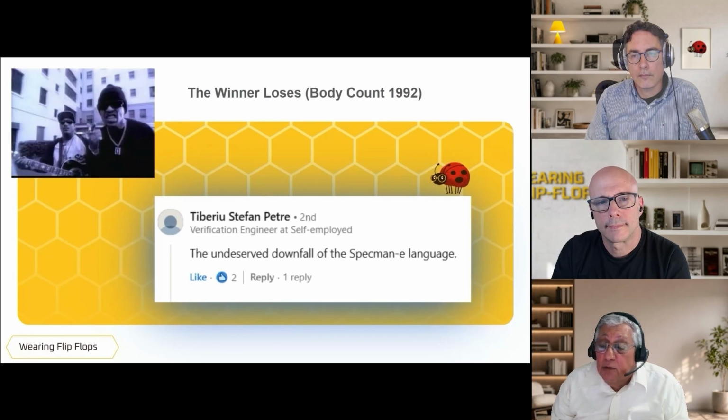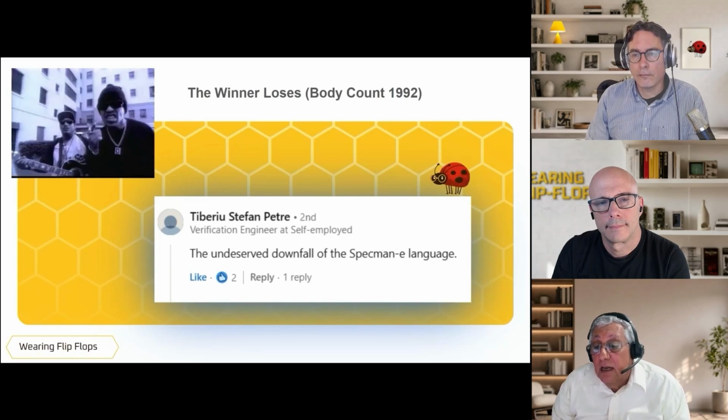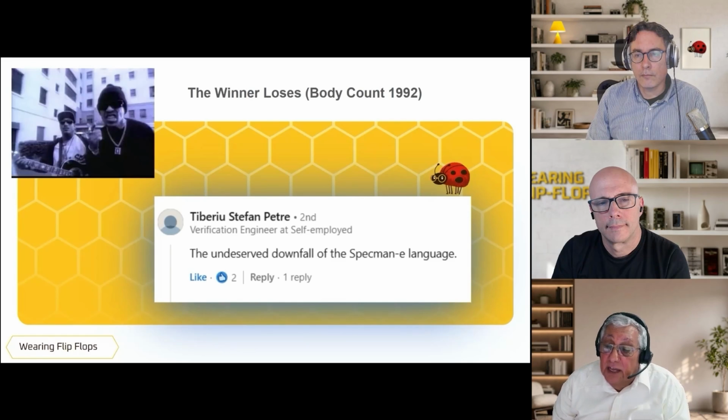For instance, you don't have to collect coverage during the whole period of developing the project, right? You might start a little bit later, somewhere in the middle of the project. This kind of thing fits very nicely to AOP. What AOP provides is the ability to add an interpreted file that adds a feature. If you don't add this file, for instance the coverage file, you don't collect coverage. To get the same thing with UVM, you always have to compile the whole thing, and with switches you configure it not to use the code.